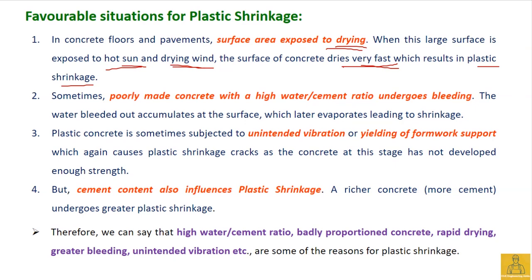Sometimes poorly made concrete with a high water to cement ratio undergoes bleeding. The water accumulated will evaporate, leading to shrinkage. This is not just with exposure; if you add more water, it is going to bleed out onto the surface.